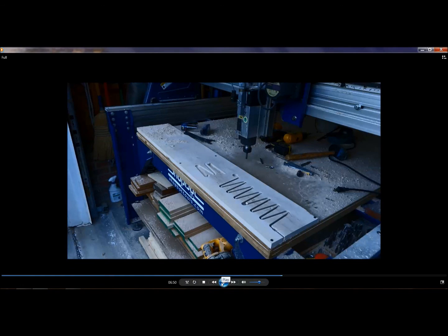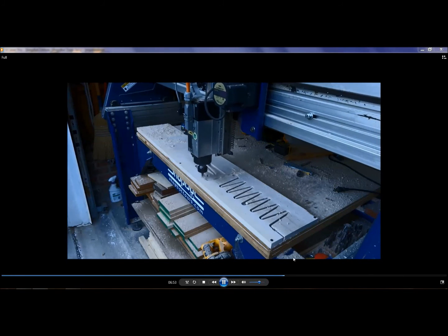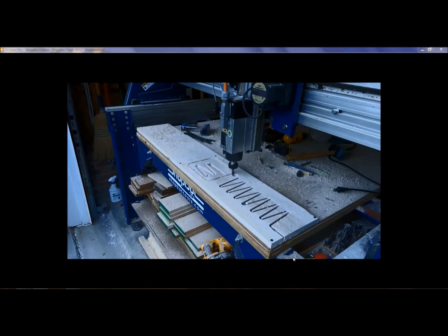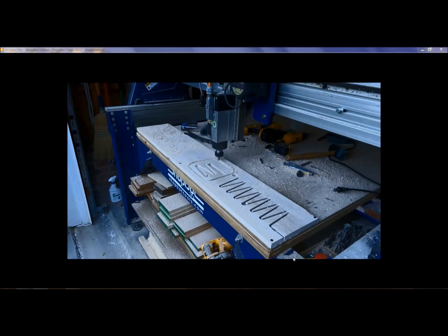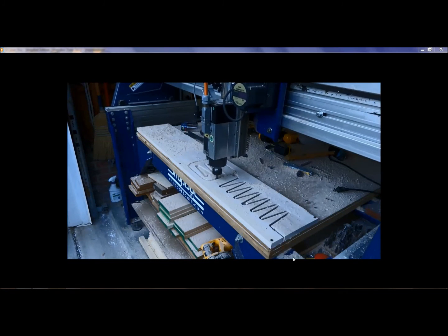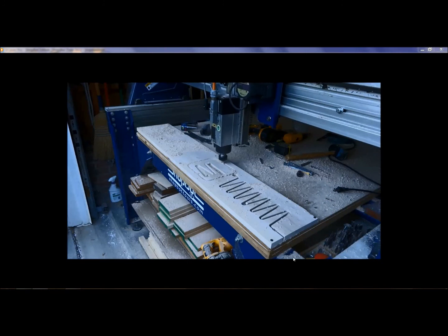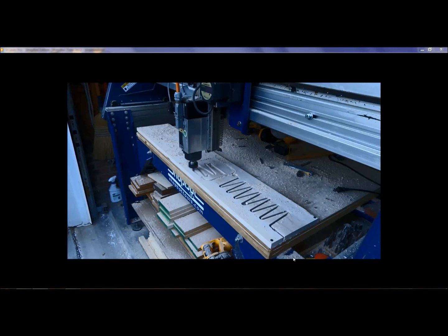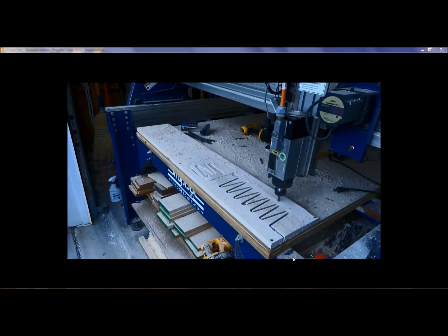And we've changed to the 3/8 compression bit here, and I also have it zeroed. You'll notice that it's ramping down over a 4-inch increment, because I had a 4-inch ramp where it ramps down in the Z. Finally, once it gets down to the final pass, it's going to start picking up right there, and what it's doing there is the tabs. Those tabs are what are holding the scrap material and the finished piece to each other until the finished cut.